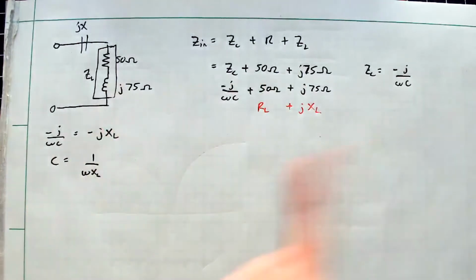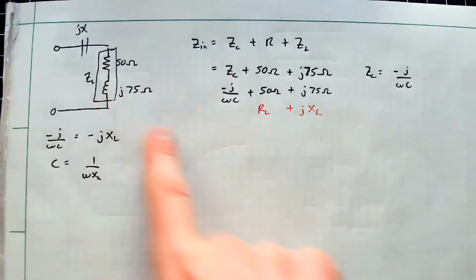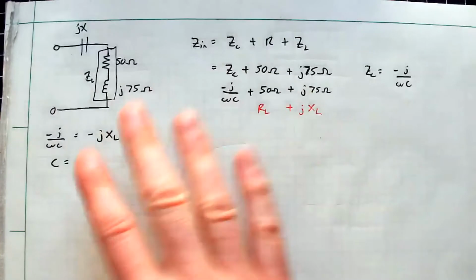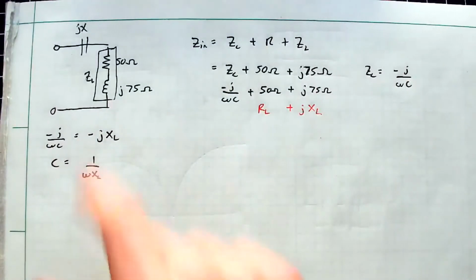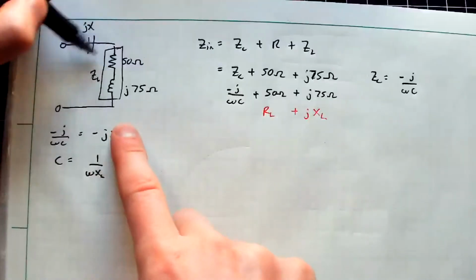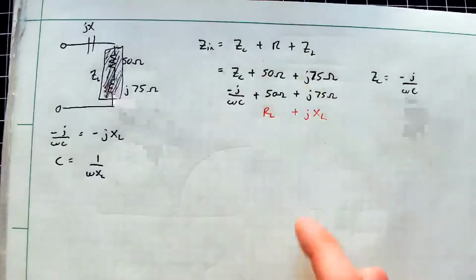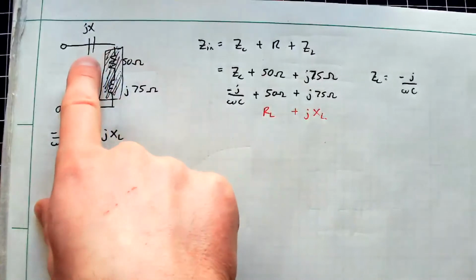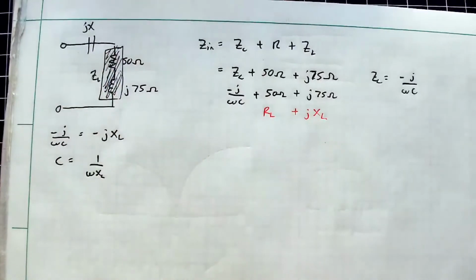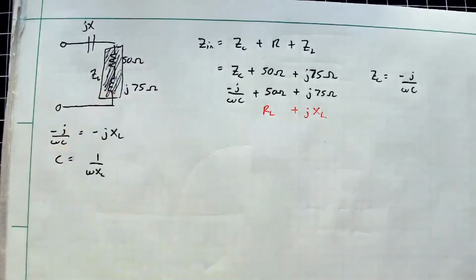This is just an example to show you what the lumped element matching is doing. I want to be able to visualize this in the Smith chart first. This is to keep it simple first, and we'll build complexity as we go. The reality, though, is it may not be a resistor and inductor. This is just going to be a black box with some net impedance, and it happened to have a positive reactance. Therefore, I needed a negative reactance in series to negate it. That's why I'm choosing a series capacitor to create a negative reactance that offsets this.